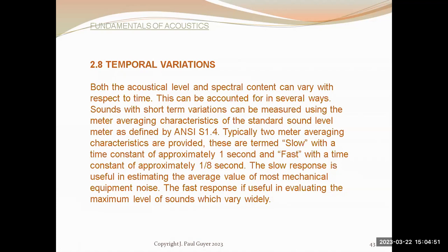So that number might be 100 decibels. But in the receiving room where the humans are located, you want to reduce that decibel level so that it's consistent with whatever the human activity is that they've got going on. They're trying to sleep, they're listening to concert music, they are engaged in a business conference or whatever.